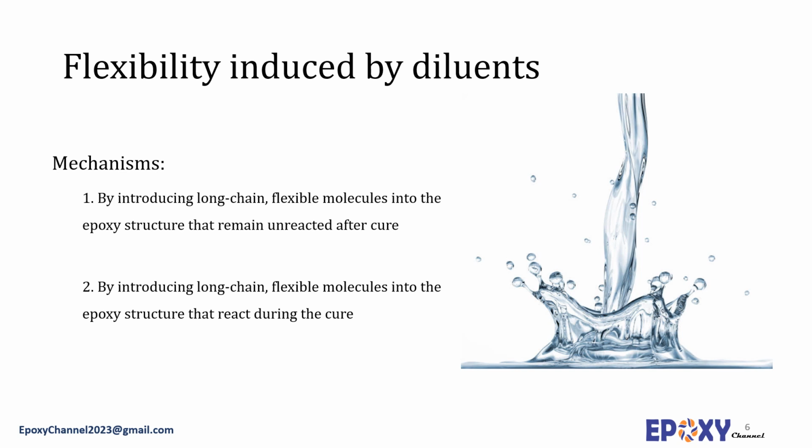In adhesive formulations, glycidyl ethers are the most common monofunctional diluents. These include butyl glycidyl ether and allyl glycidyl ether. Other effective monofunctional diluents are epoxidized vegetable oils, olefin oxides, styrene oxides, and pinene oxides. Di- or polyfunctional epoxy resins may be considered reactive diluents that provide a degree of resiliency, yet most preserve the inherent properties of the base epoxy resins.